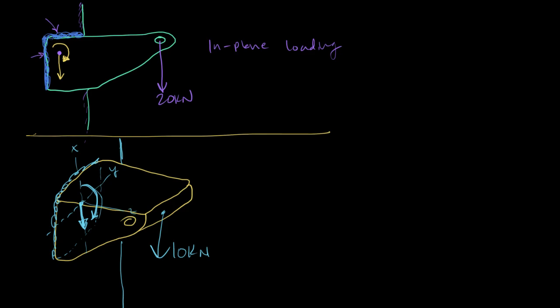You replace it with that load and then that bending stress that's applied. Then you look at the bending stress that would be applied from this position relative to that center of the weld group, and do the analysis that way. So these are assumptions about how we analyze this, and this is sufficient for most engineering design work.